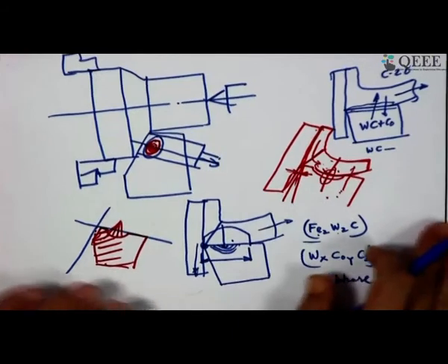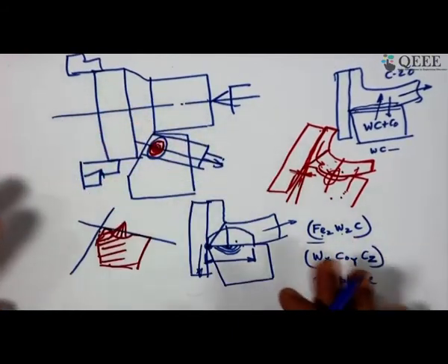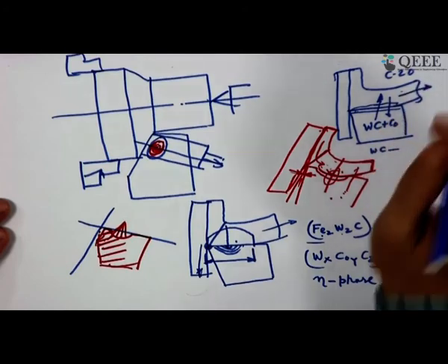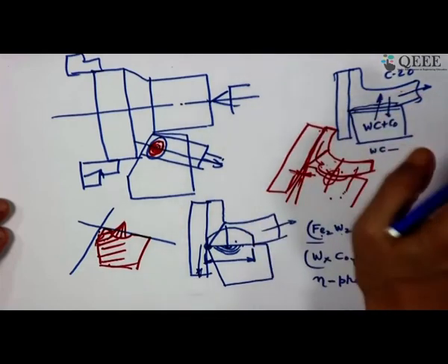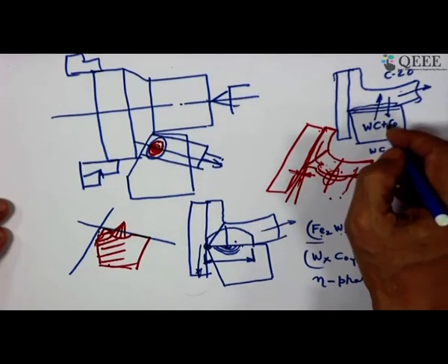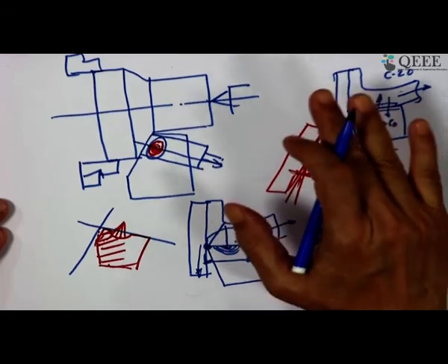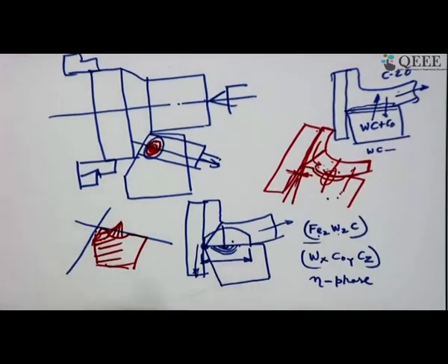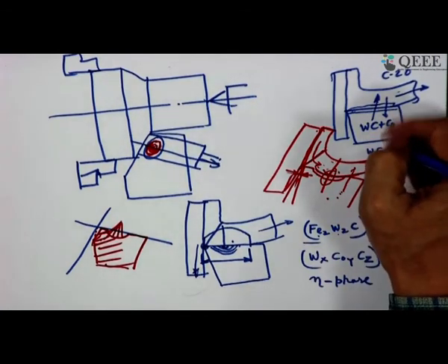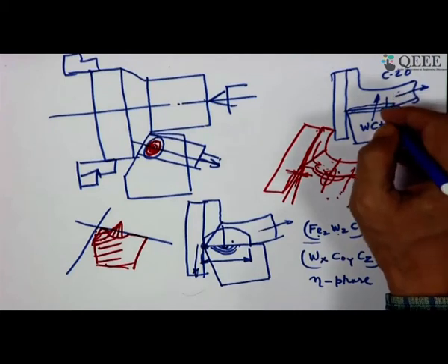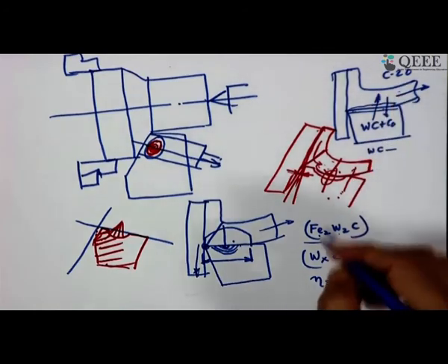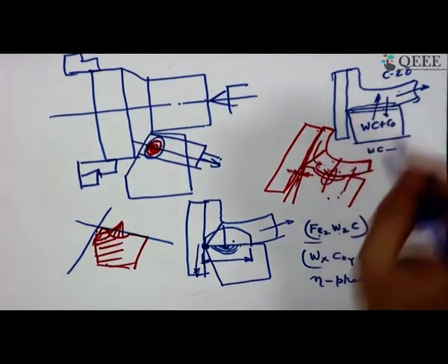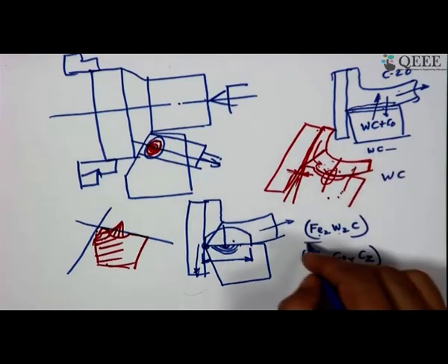So, friend, originally if you look back, it was C20 steel rubbing over the tungsten carbide cobalt cutting tool material. But because of this dissolution and diffusion, you have enrichment of the layer of this chip which is in contact, and it becomes enriched with carbon, it flows, and then on the top surface of the tool it is no more tungsten carbide, it is now this layer.